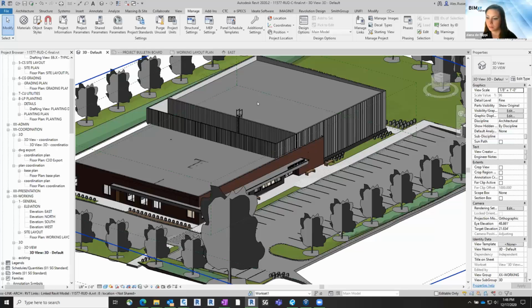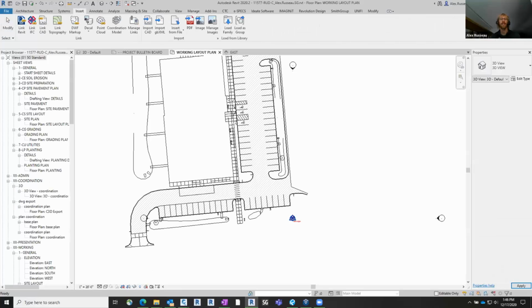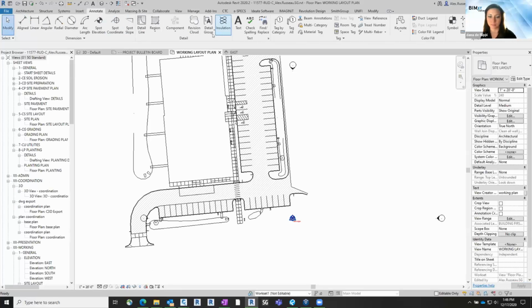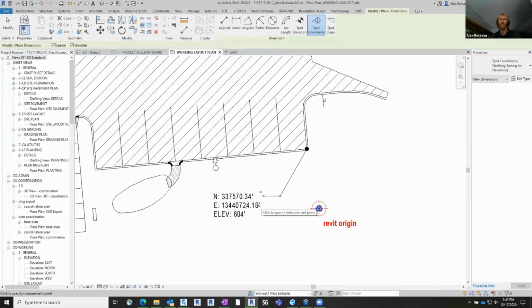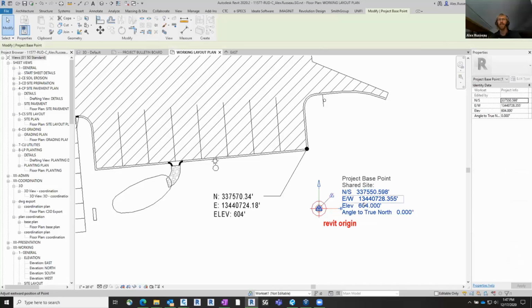Absolutely. And then can you specify coordinates at a point? In the Revit model? Yes, I guess so. Heather, I mean, you can annotate if that's what the question was. So you can do a spot coordinate and you can check it. And there we go. We got actual points. So you can, in your modeling, show those building corners with coordinates. And would that be the same as entering the data? I feel like entering the data would be these. I might be getting the question wrong.